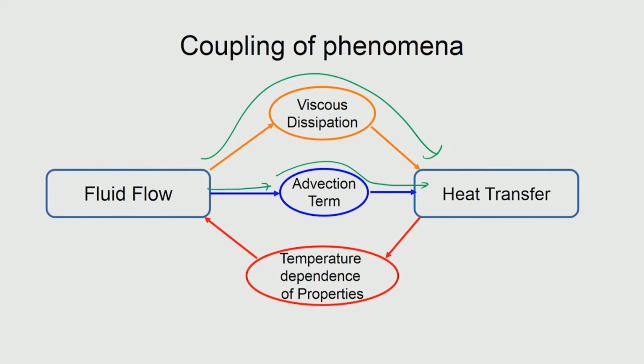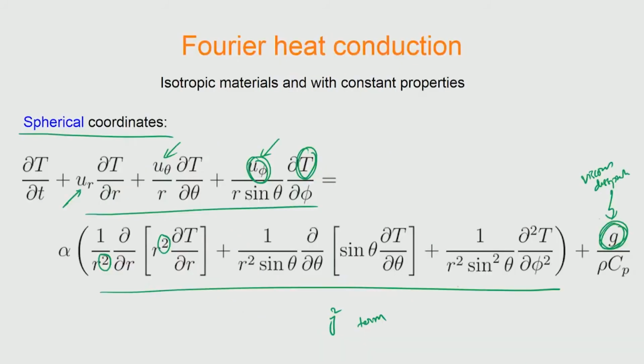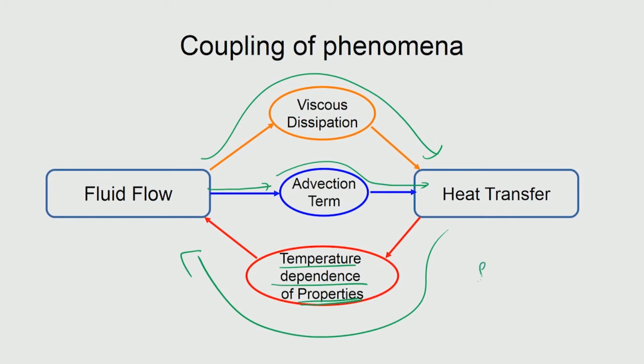Now, how does heat transfer affect the fluid flow? That would actually affect via the properties. So, you could see that it is actually affected via the temperature dependent properties. Okay. So, if you have, for example, rho that is dependent on temperature, then it will lead to what is called buoyancy flow, and if you had, for example, surface tension that is dependent on the temperature, you would have what is called the Marangoni fluid flow, etc. So, like that heat transfer can lead to fluid flow, and fluid flow can lead to heat transfer, and in such a coupled situation how do we go about?